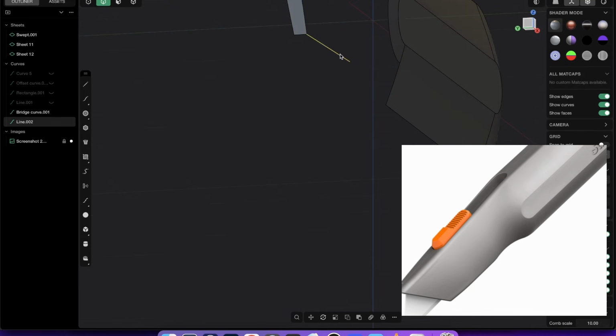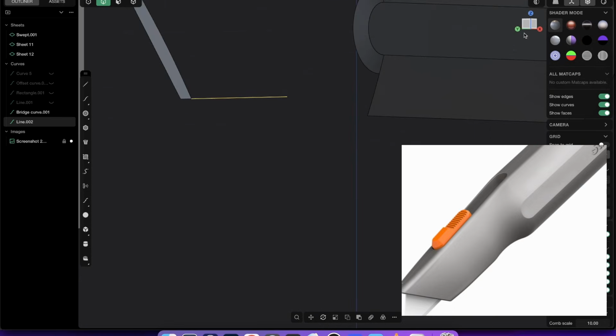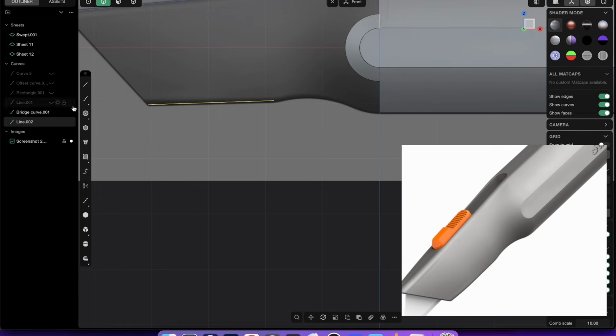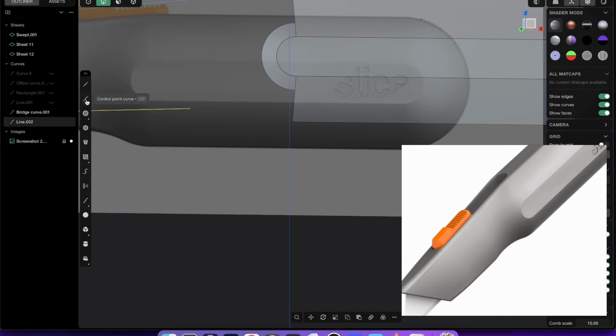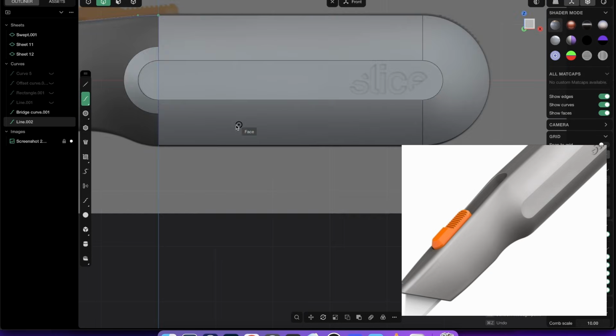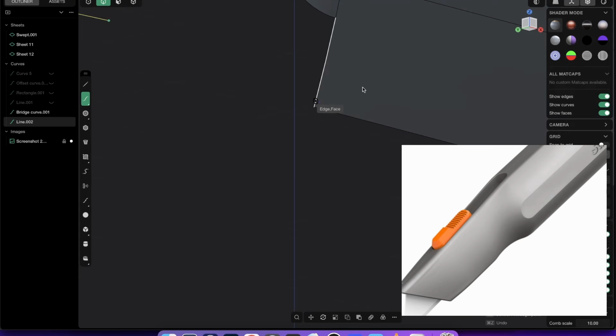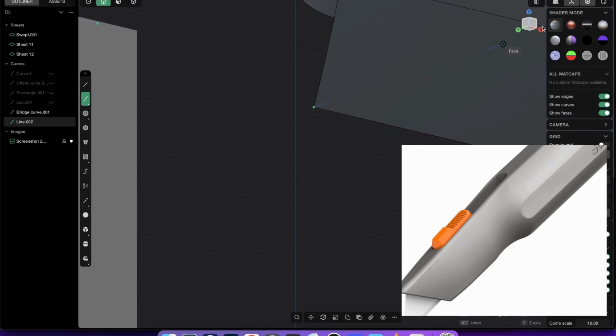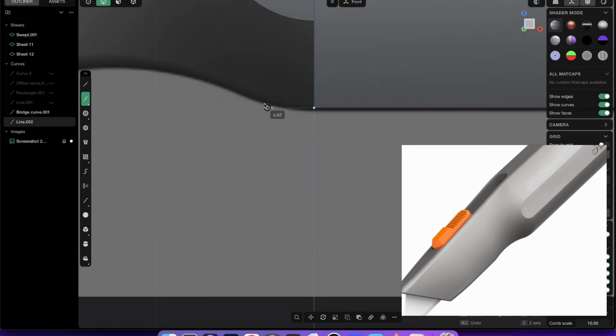So you see we have to connect this curve with this edge. And just a very simple way is, if you go to the control point curve, so select this and go to the control point curve, again front view, and just make sure that you snap here and just drag that out on the x-axis, so we will have again G1.